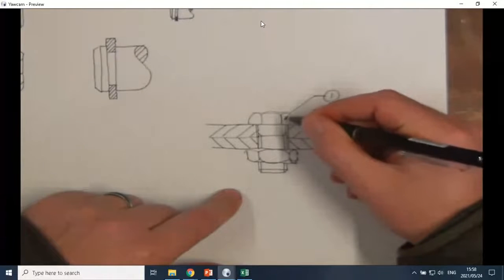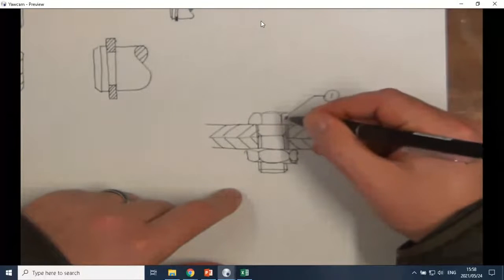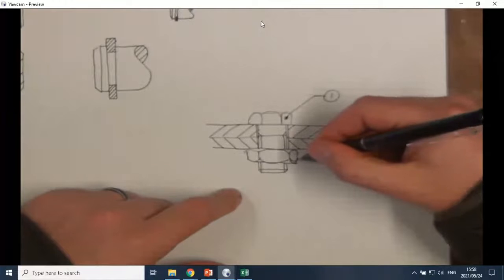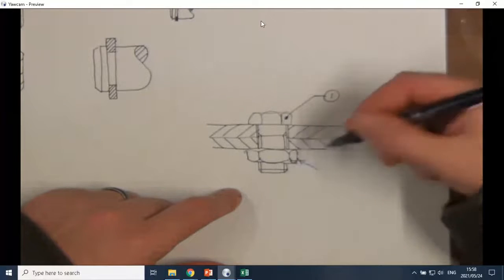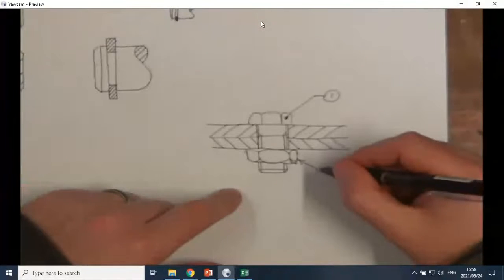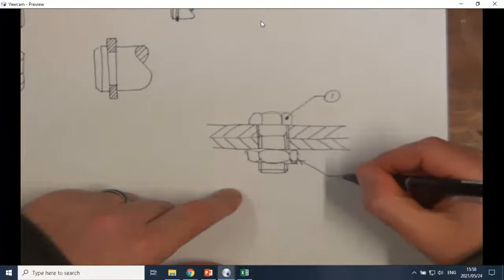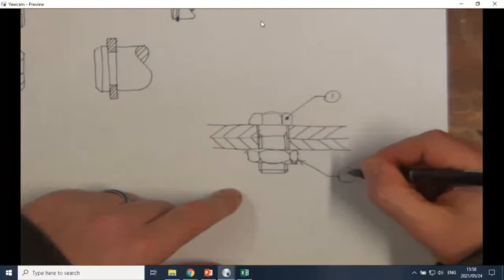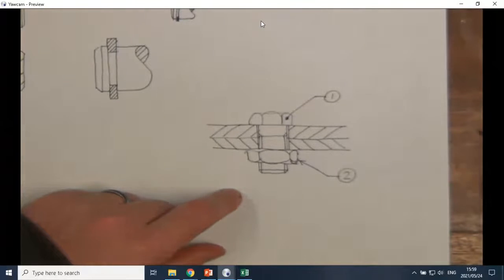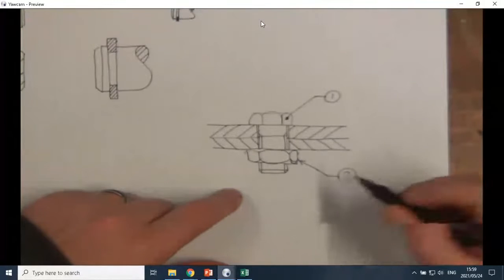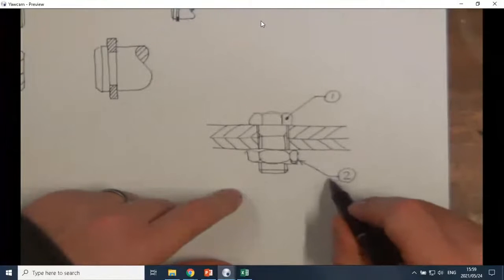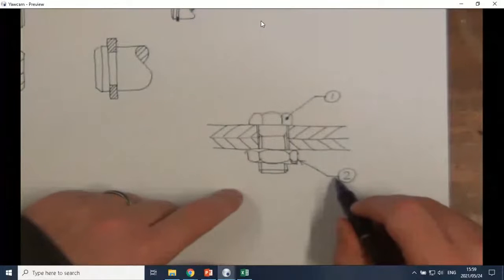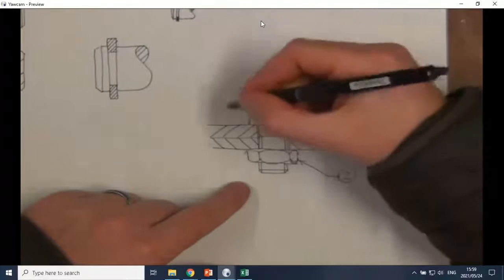If you don't want to refer to a surface, let's say it's too small to put the big dot on it, you can make use of an arrow and put the number in the balloon with the short horizontal portion. The horizontal portion, however, is not a specific requirement.